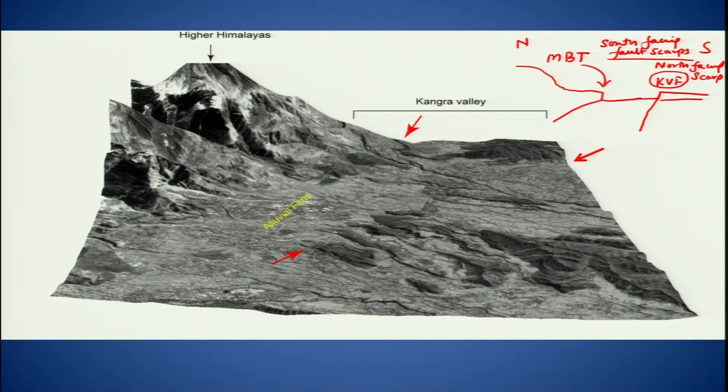So what other features we were able to pick up, I'll talk in the coming slide, but before we entered into the digging trenches and all that, we wanted to understand in what way the environment got affected, which prevailed on these alluvial fan surfaces. So you have alluvial fan surfaces here, and if this was the faulting pattern, and you take the general slope of the area and then you are uplifting something here, then whatever the drainage is coming here will get blocked here.